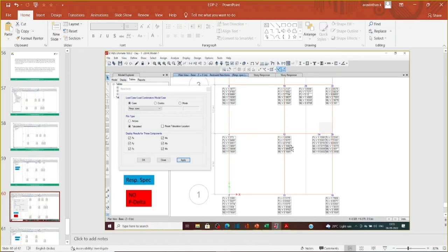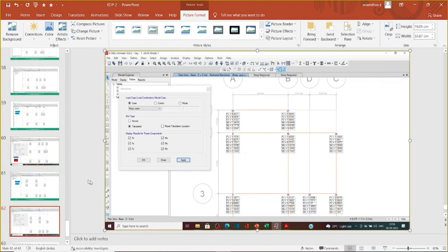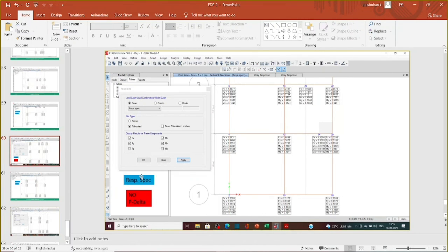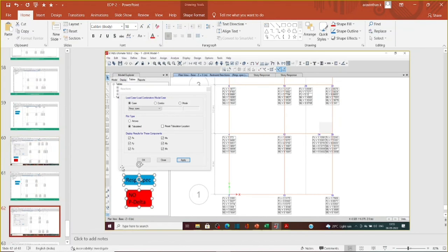The moment is much lesser here, 2.21 and 2.2807. Why the deviations are very much less is since you are having a D+1 story, the moment is also reduced. This is without the P delta effect. Response spectra for no P delta.